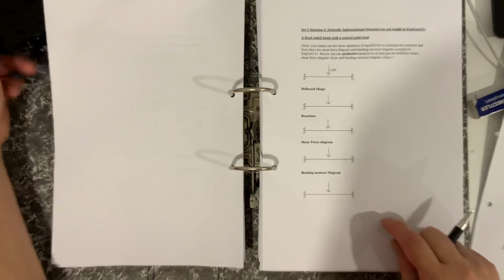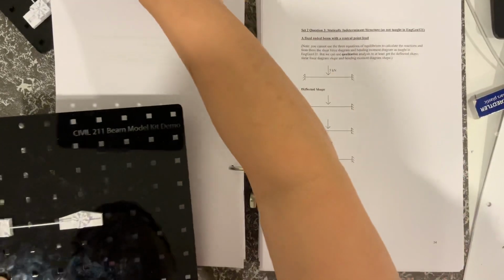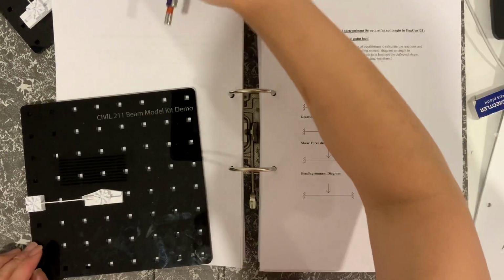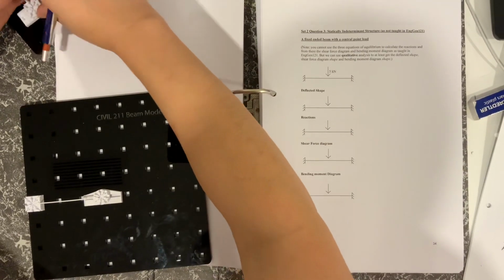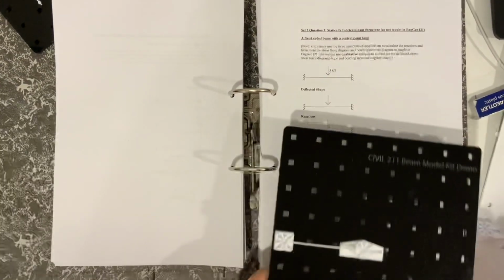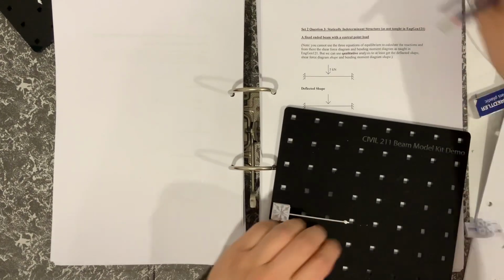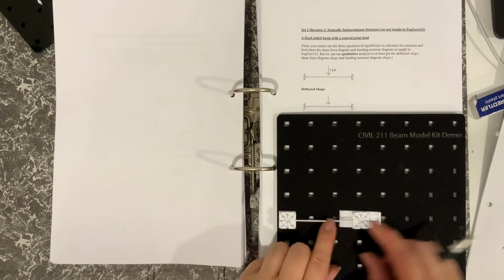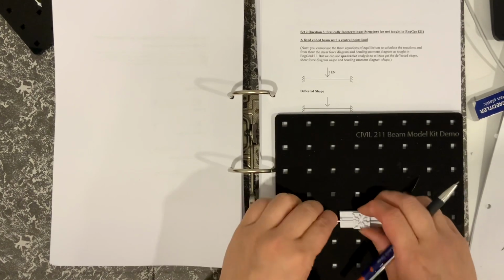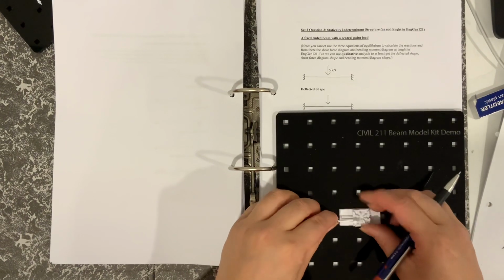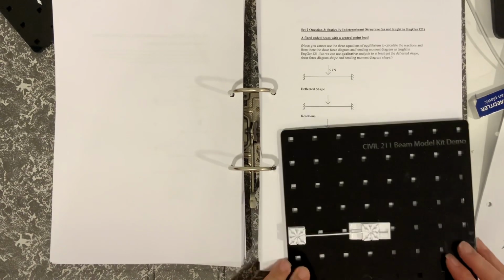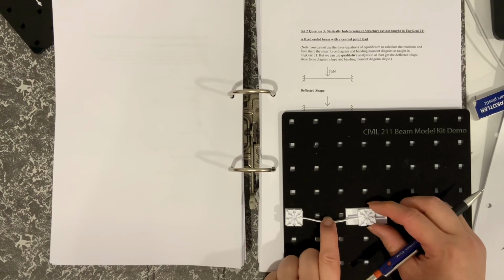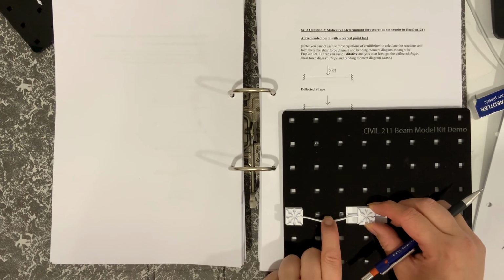Next one here is what's known as a fixed-fixed beam. It's drawn like that, but technically speaking, because we don't want to get that catenary action in the beam, one end is actually assumed to be able to slide, which is fine, this way. So central point load, symmetry of course, so we can see that the thing is going to be symmetrical.